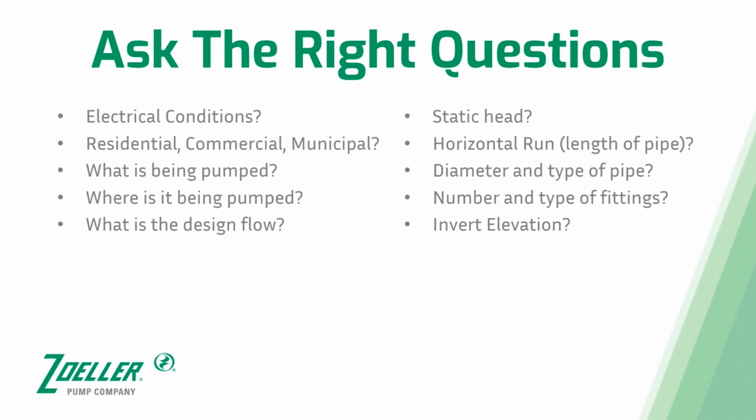So this is not really a pump sizing course, but I will give you the right questions to ask when you are trying to make a pump selection, outside of just what you're pumping. You need to know what your electrical conditions are in your application. Specifically, are you using 208 volt power? Is there going to be 230 volt power? Will there be single phase or 3-phase power available? Pumps are typically going to be designed and ordered based on this specific electrical condition.